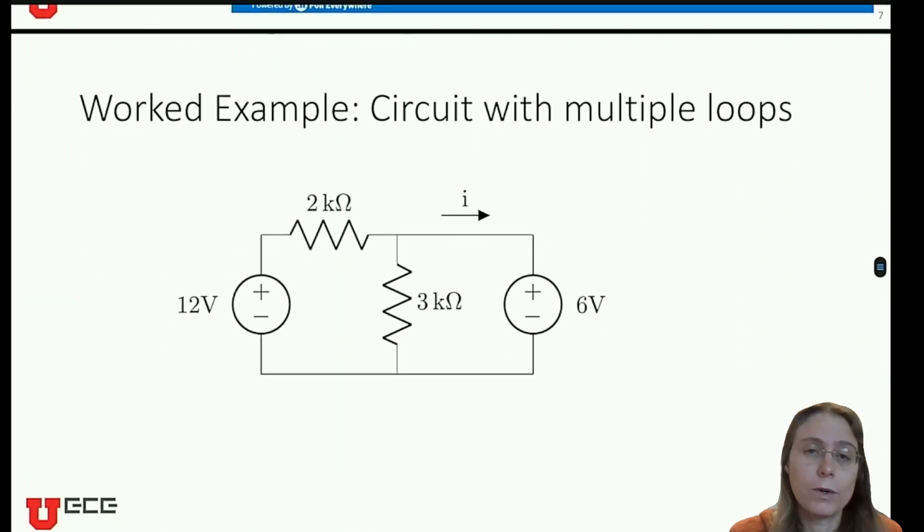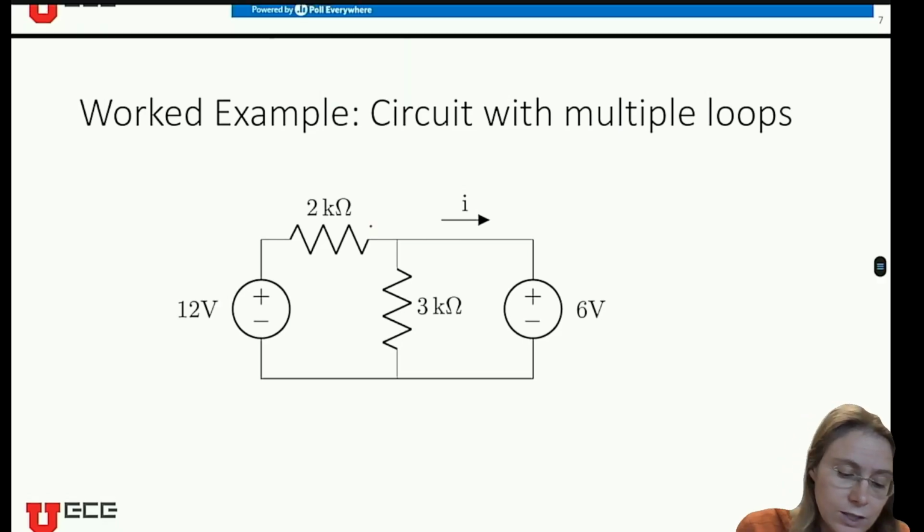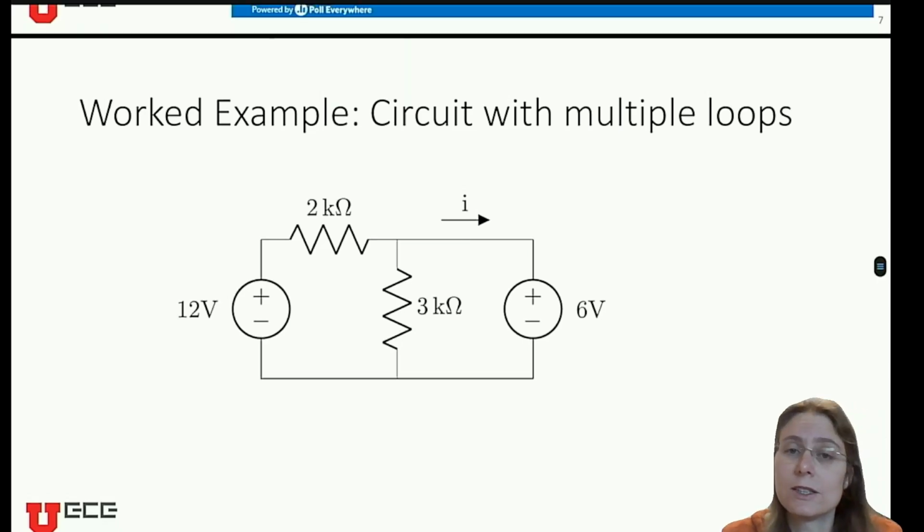Okay, I have one more example to show you today. And this one is going to combine both our Kirchhoff's current law and voltage law, and also Ohm's law. And we're going to have to use multiple problem solving steps. So I'm sitting here and looking at this circuit kind of wondering, like, what pieces of information do I know that will give me some other voltage or current in the circuit? So for example, right, if I'm at an intersection here, if I know 2 of the 3 currents, then I can get the third one.